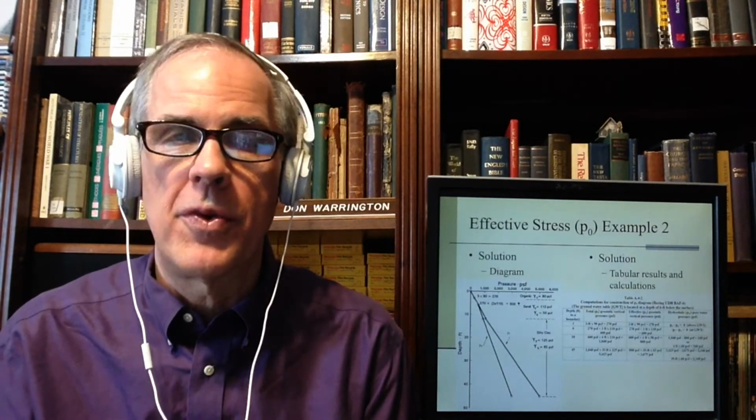And they come up with pore water pressure, which would be different. You can check it for yourself than it would be if we just did the standard. One thing that you might want to go back and look at to see that this actually happens in reality is that the cone penetrometer test, for example, monitors pore water pressure as it's being pushed in the ground.